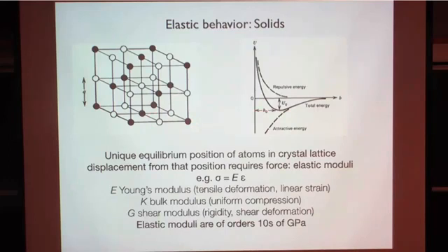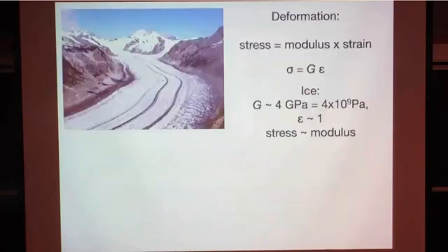And that's important. You can see that the springiness might come from the fact that when you try to compress this, for example, you're trying to move this equilibrium position up the potential well, essentially. So that's the resistance. That's, in essence, very, very simplified, where this elastic modulus, the spring constant, comes from. So deformation then. Here's Hooke's law again. Stress is modulus times strain.